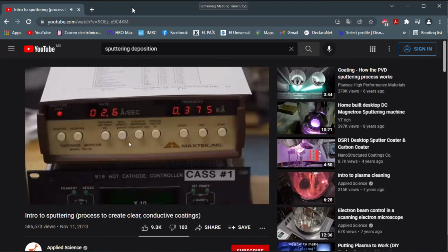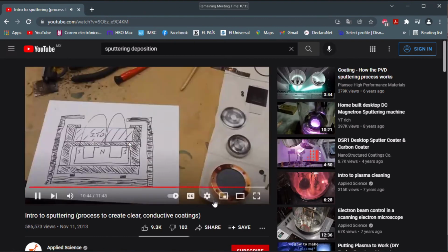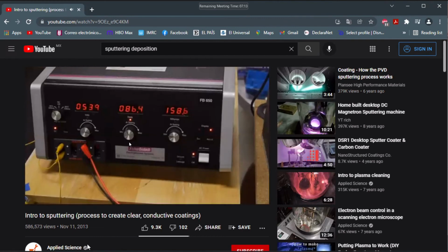In my first few experiments here, I've noticed that controlling the pressure is actually surprisingly difficult and also, as the literature says, has a pretty profound effect on how the sputter process is going. I've been using an electrophoresis power supply for my first attempts here, and it turns out to be a very non-ideal power supply for this purpose.